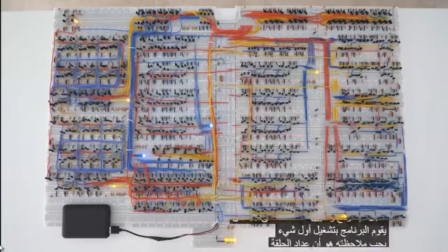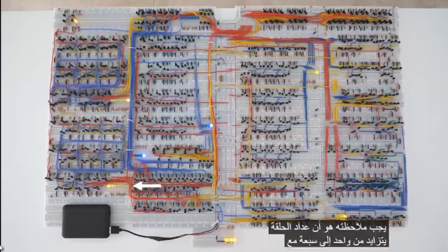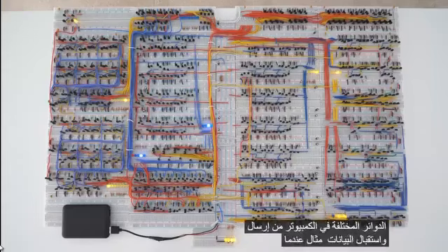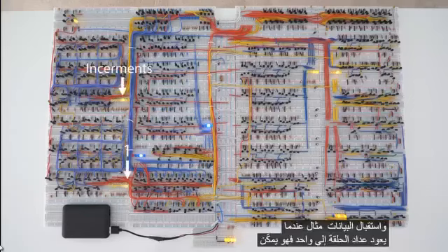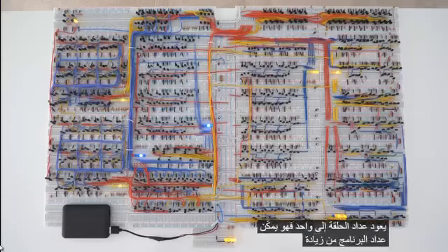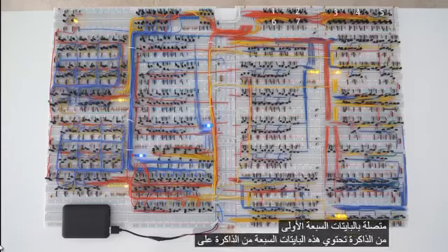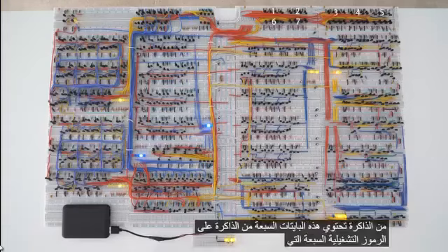The first thing to notice is that the ring counter is incrementing 1 to 7. As the ring counter increments, it enables different circuits in the computer to send and receive data. For example, when the ring counter goes back to 1, it enables the program counter to increment. The 7 values of the program counter are connected to the first 7 bytes of memory. These 7 bytes of memory contain the 7 operational codes the computer is running.